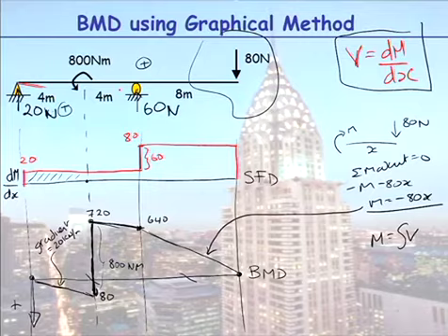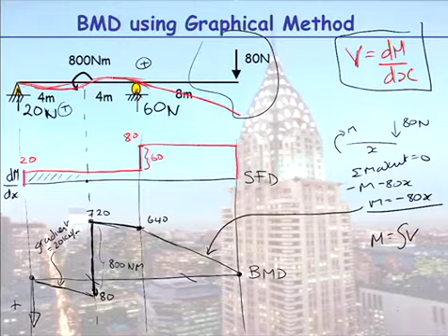So whenever you're asked to draw the deflected shape, you're asked to sketch it, which means just give us some idea of what you think it looks like. So I would say I've got tension on the bottom and I have to have a point of inflection here. Oops, so I'm not doing a good job of this. How does that look to you? Pretty crap. Okay, so there's a point of inflection here, because a point of inflection corresponds to where our moment passes through 0. And that would be my attempt, I'd draw it a bit nicer than that if it was on the test, at the deflected shape.